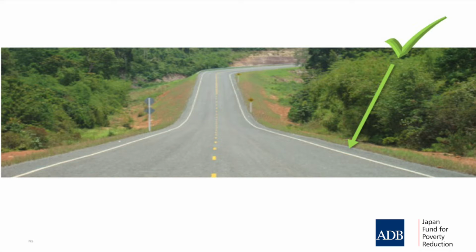It's a small increase in the cost overall of building a road. If you can provide even small sealed shoulders, just enough for a rider to escape. Because if they go into the gravel, the dirt, a drop-off, they come off their bike. And if they come off their bike at speed, they're in trouble.